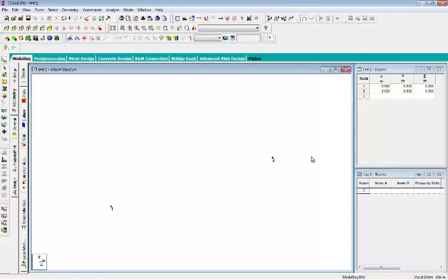In order to add a beam, you just have to go to the beam cursor. Generally by default we have the add beams option. We have to go to this add beam. Fine, then just click at 1, go to 2, and we have a beam out here.